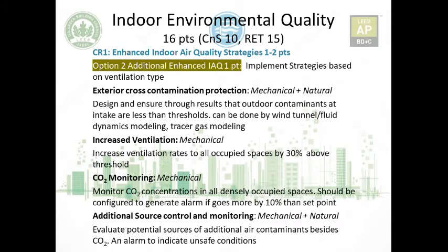inside. If you remember, we put the CO2 monitoring in the natural ventilation because of the fact that with the breathing, the CO2 levels may get high. And with mechanical, it's not a prerequisite, because in mechanical system, air is being exhausted by your mechanical ventilation systems. But in order to put additional enhanced IAQ, you monitor CO2 concentration in all densely occupied spaces, and similarly it should also generate an alarm if it goes more than 10% by the set point.